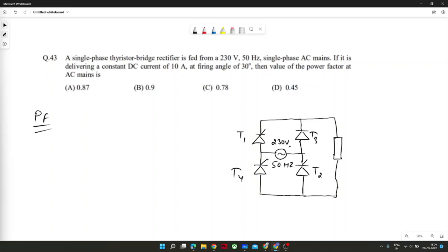And the other is the harmonic components, let's say third harmonic, fifth harmonic, and so on. So power factor is the angle between V1 and IS1. This is known as fundamental power factor, or you can say cos alpha it is known as.